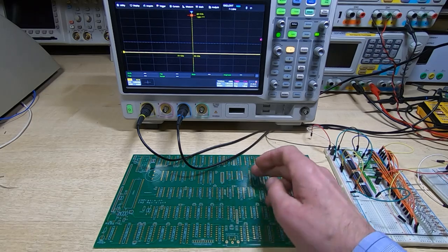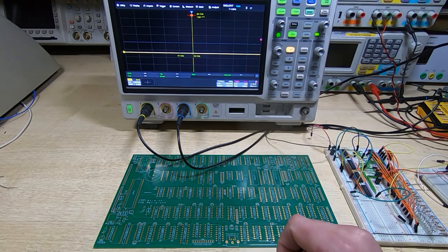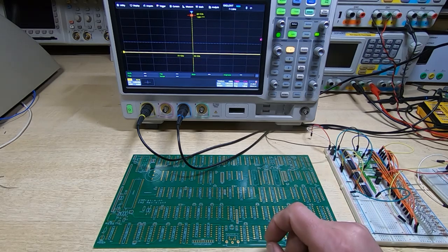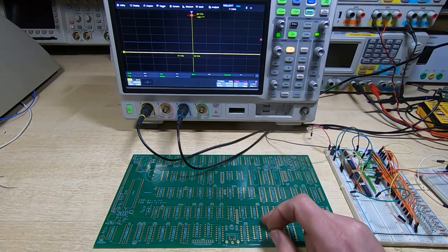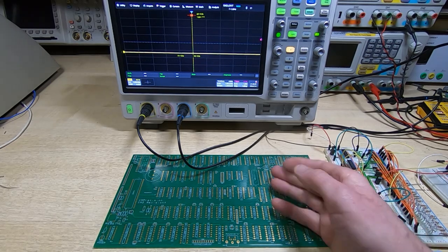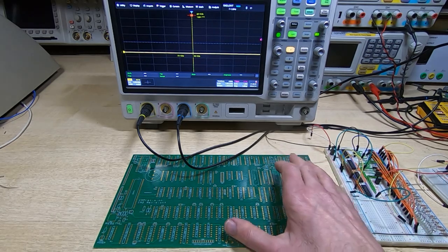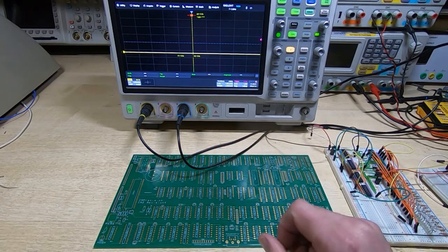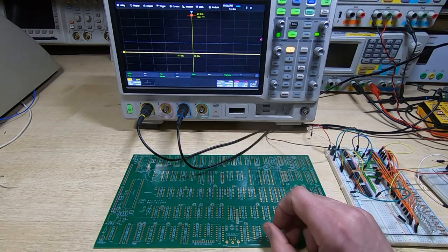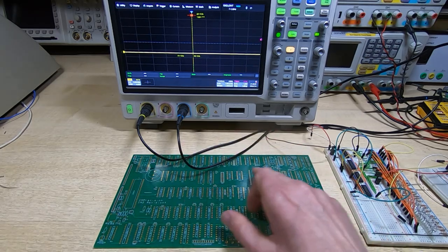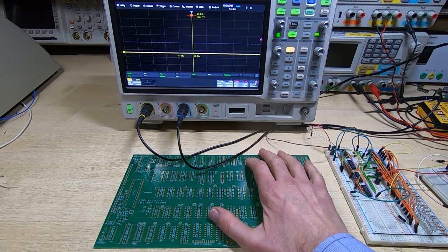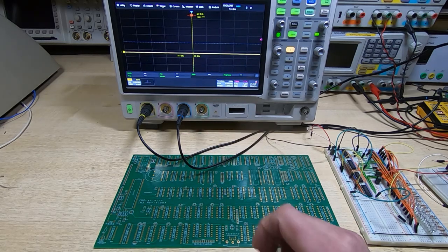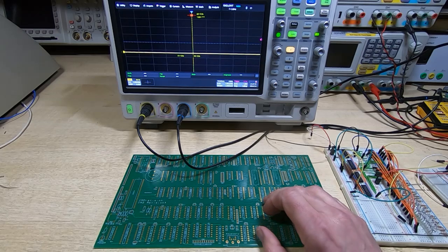What I ended up designing was splitting the data bus into 3 separate buffered data buses, and they can all be controlled independently. And the reason I went for 3 buses is so I didn't end up with another fan-out issue as we add more devices. And that means that the design from this board to the next board is quite a big step, because it completely changes the way that the Z80 is connected to the rest of the circuit. Most of the circuit can be kept the same, but the buffering of course changes things quite a bit, and if I make a mistake in the way it's controlled, the new board won't work.